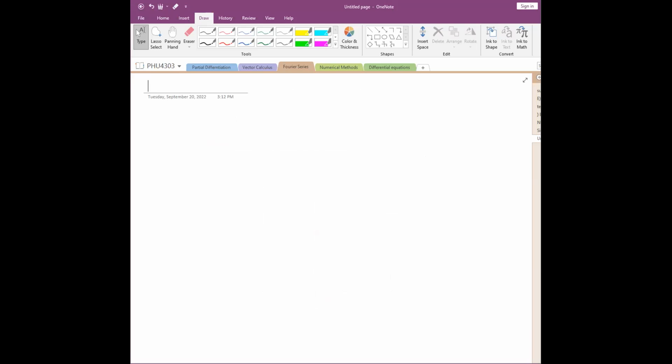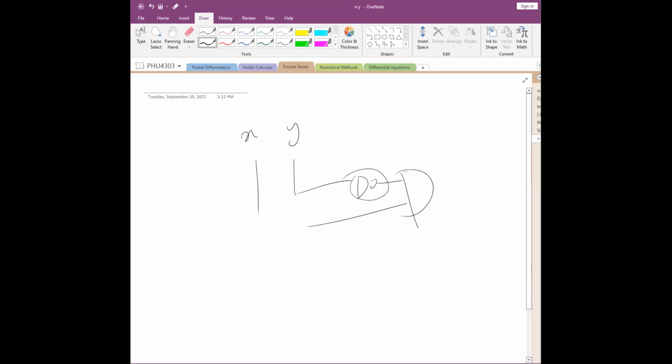So what I'm saying is in your circuit, you have X and Y as inputs. In some cases, you have NOT gates like this, and in some cases, you don't. So rather than putting NOT gates here every time, we can have a single NOT gate here. So this will be X bar, this will be X. Similarly, we can have another NOT gate here. This will be Y bar and this will be Y.